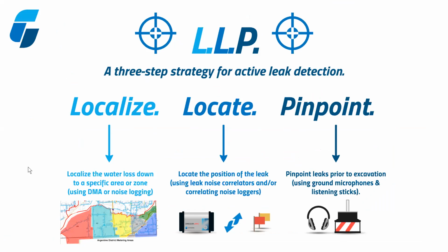Yes, if you're sending your data up to ZoneScan.net and your GIS data that's on ZoneScan.net is accurate, and you can trust your GIS person that they put in accurate data, then ZoneScan.net will just use the data that's embedded in that GIS, and you will get your pinpointing. However, it's not a perfect world we live in. Now and then your GIS data might be inaccurate, wrong size, wrong material. In ZoneScan.net, you can actually go in and manually change your GIS pipe segment to a different material to allow ZoneScan.net to accurately correlate and pinpoint the location of that leak.